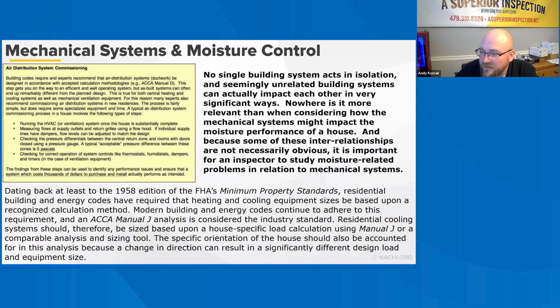Home inspectors should recommend that all exhaust vents be directly vented to the outside by attachment of the exhaust vent ducting to appropriate through-wall or through-roof ventilation fixtures or grills. Exhaust ventilation ducts should also be attached and supported like any other ductwork.